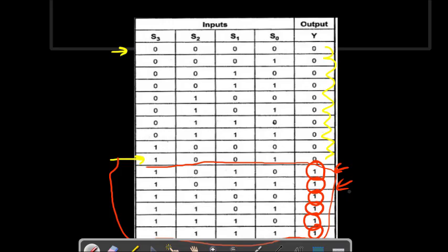So this is the truth table for applying that logic: up to 1001, that is up to 9, we are getting a valid BCD, and beyond 9 we are getting an invalid BCD. So we must add BCD 6 to that digit. So we'll draw a K-map for this.